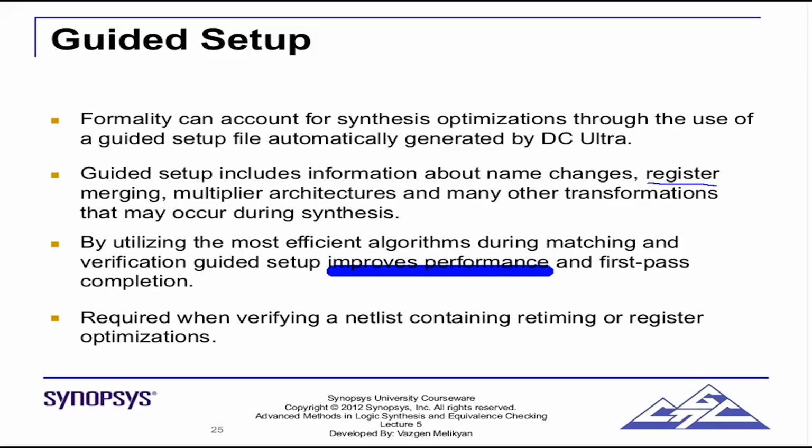Now in that case, if you debug that, retiming happens for the case where the combinational logic is too much, right? Then only retiming will happen. Retiming is there to solve the timing problem majorly. And when is the timing problem? Mostly when there is a big combinational logic, and when there is a big combinational logic, the logic cone will be very big. So debugging such problems, such logic cones are huge, and it will take you days to debug the problem if you do not use guided setup. So this is where guided setup is very useful. It's a very useful feature of formality.